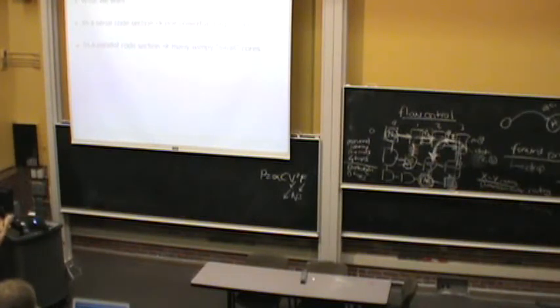So for a parallel code section, you want those wimpy cores. For a serial code section, you want a single powerful large core. But the problem is these two conflict with each other. If you have a single powerful core, you obviously cannot have many cores. And why? Because a small core is much more energy and area efficient than a large core. You may not want to have large cores.